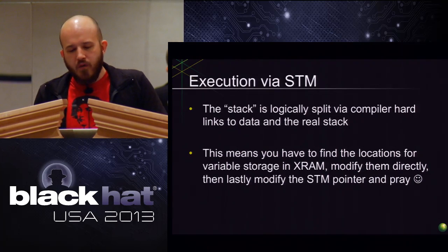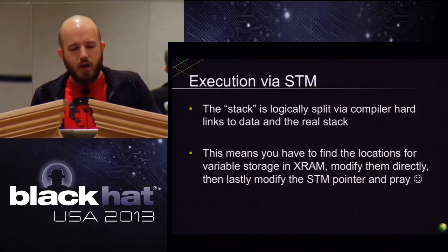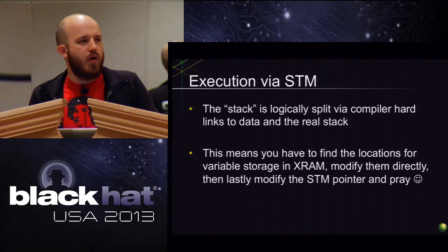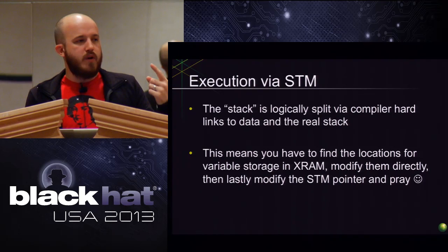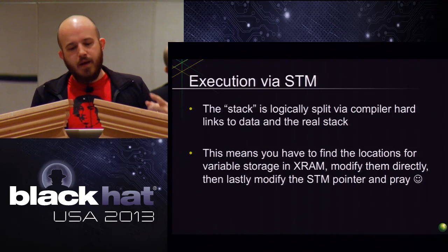Well, that's really hard. So you've got to figure out where the locations for variable storage are, or you have to find which functions are actually using variable storage in static locations in external RAM, which happens most of the time because of the compiler. And then you modify those.